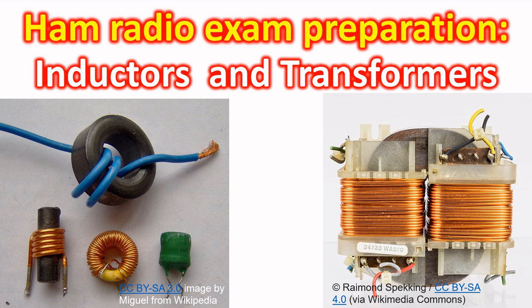An inductor is simply a coil or loop of wire which opposes a change in the current within it. Inductance of a coil is measured in Henry. Inductance of a coil will depend on the number of turns in the coil, permeability of the medium inside the coil, cross-section of the core, and the spacing between the turns of the coil.